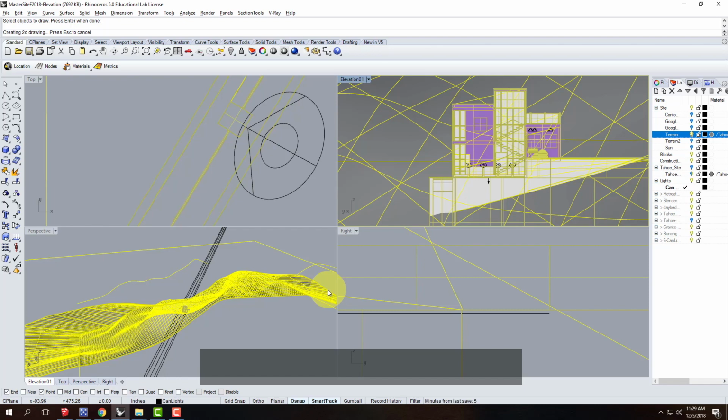If you run into trouble at this point, when you're trying to do the Make 2D, try turning off your furniture or any complicated objects that aren't really necessary. I probably should have done that, but I didn't. Because it'll have to go through and calculate out the hidden lines of your furniture. You have a couch and you have lines behind the couch. It'll figure out what's hidden from view, etc. So it can get a little daunting while it works. So I'm going to let this run for a bit.